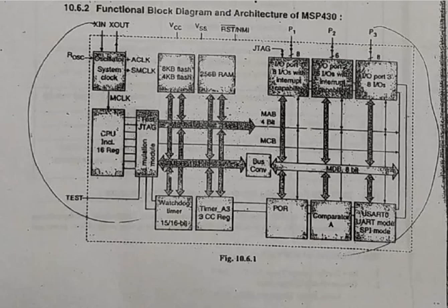The MSP 430 has 16-bit registers. Some of the instructions can work on both 16-bit data as well as 8-bit data, while some others can work only on 16-bit data. The instructions are basically of three formats, namely source destination format, single operand format, and branching format instructions. The instructions according to these three formats support byte as well as word operations.